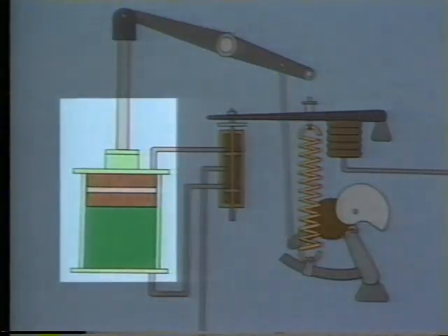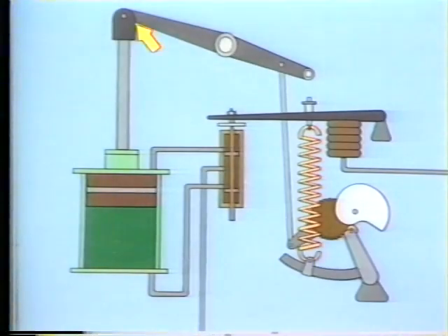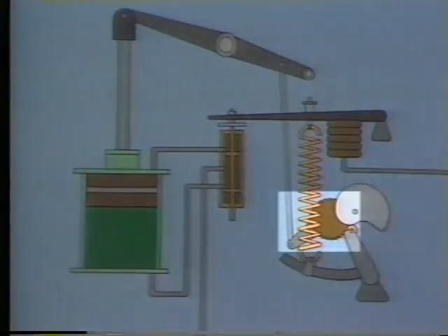But the purpose of a positioner is to position the actuator according to the control signal it receives from the controller. Now, sometimes this may be all the way up or all the way down, but sometimes it will also be at various positions in between. This is where the feedback that we mentioned earlier comes in. The piston actuator is connected to a series of mechanical links that move as the piston rod moves. These links are connected to the positioner at this drive arm. In this positioner, this drive arm and gear meshes with a smaller gear.